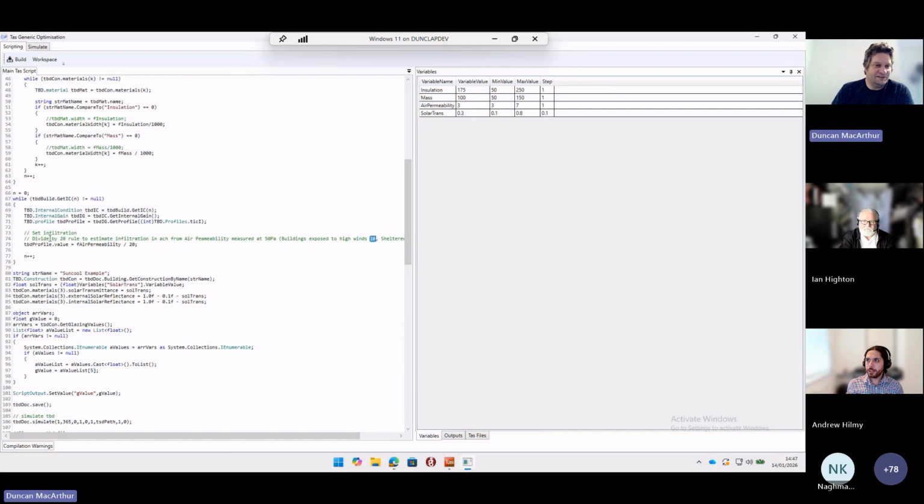The other thing is, based on your air conditioning system, you might expect that when that's on the infiltration drops, and so there's lots of different options there for how you want to model the infiltration. But I've just set an air change rate, and that will be all the time for the zone.